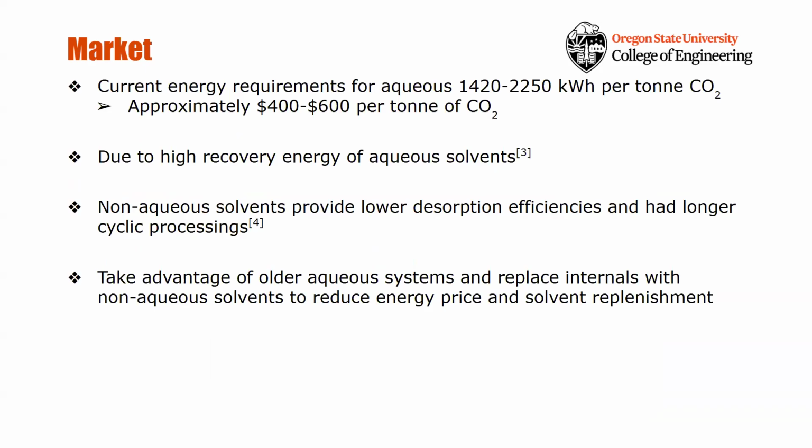As Mark was saying, the biggest economic constraint for this issue is the energy cost of boiling the CO2 out of the solvent. That is mainly due to the water-based solvents being aqueous, so we are looking at non-water-based solvents. Other methods for carbon capture include solid media and membrane, but we're not looking at those for multiple reasons. Liquid state seems to be the most efficient in terms of energy consumption.